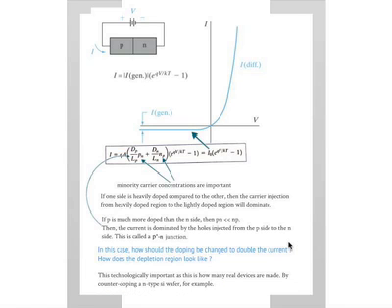And the reason for this, and we skipped that portion of the chapter in the interest of time, has to do with the fact that you start off with the silicon wafer. Remember, it's a silicon wafer which gets processed to make the transistors, diodes, whatever. The starting silicon wafer tends to be some lightly doped material, like N-type. It can be P-type, let's say N-type, okay? Then you make your diodes and so on, which means that you introduce a P-type doping into an N-type substrate. So you start with a silicon that's N-type, and you dope it enough with P-type dopants, and you make it P-type. Okay? So you end up with a P plus N junction.